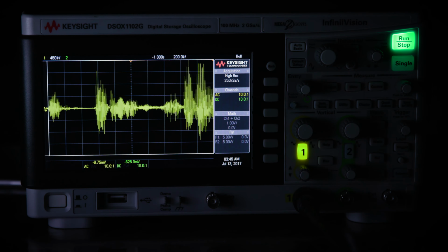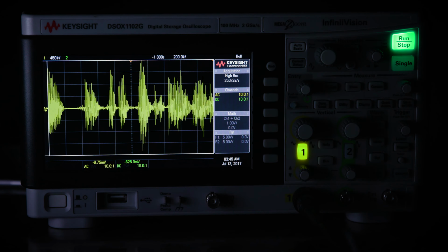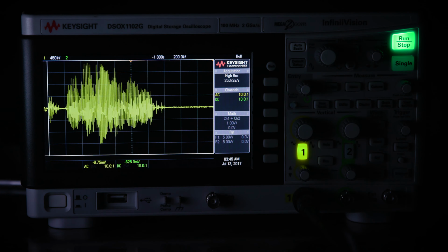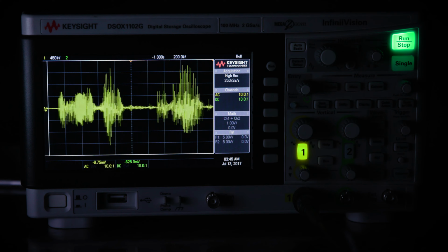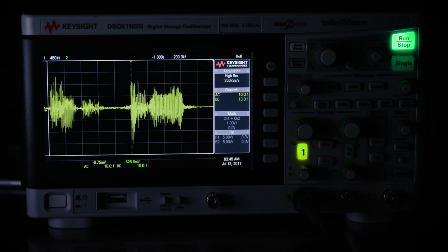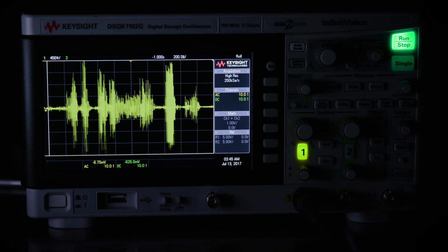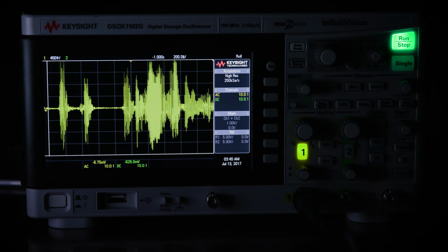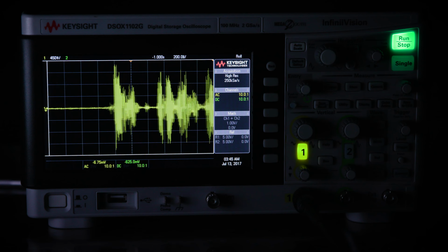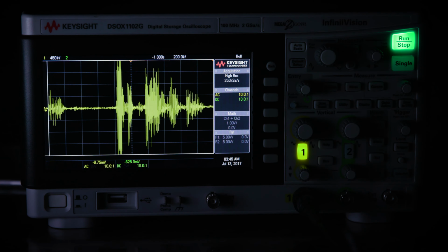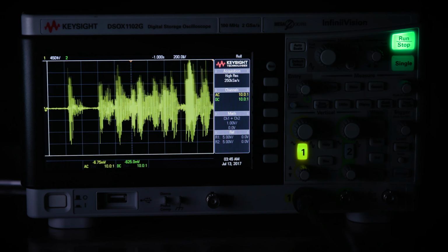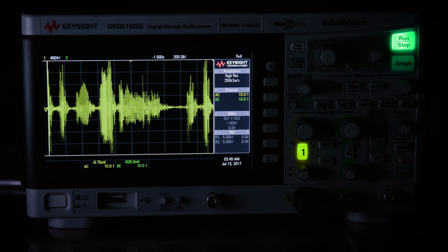Without revealing trade secrets, can you talk a little bit about interleaving and how that works? How do you coordinate that? Sure. If you think about it very simply, you have an A to D converter. If you want to double your sample rate, you put in two A to D converters and feed both from the one system. But you have two problems.